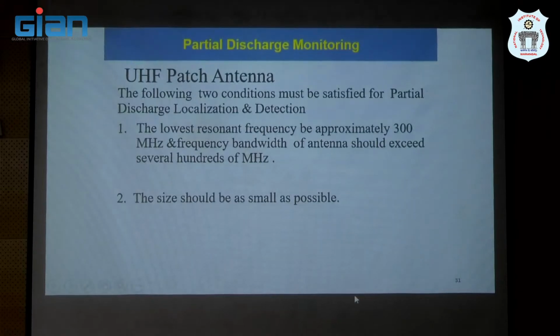Sometimes for other types of power equipment, such as transformers, they can place the sensor at the drain valve, at the oil point, or they can use dielectric windows. In dielectric windows they place these sensors and try to detect, rather than placing them inside.